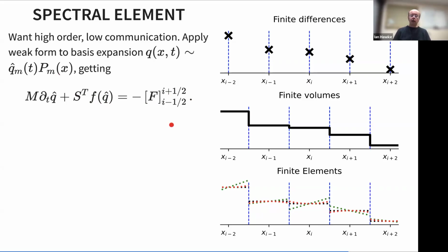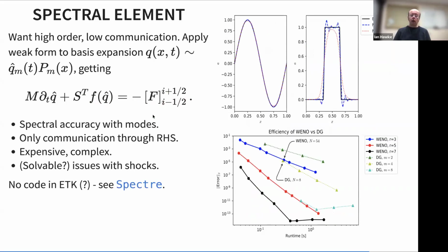And then finally, we've done a weak solution, so we're integrating over the cell. So this term here comes from the boundary terms, the communication between neighboring cells. Okay? So the key advantage of this method is that we do not have a large stencil. All of this here uses information purely available inside a single computational cell.